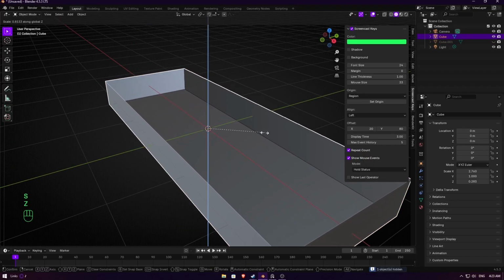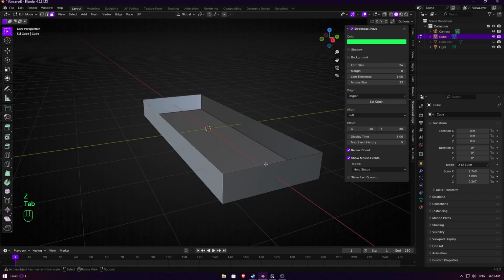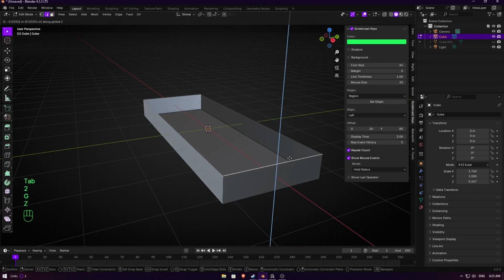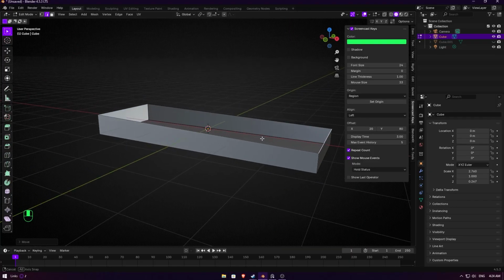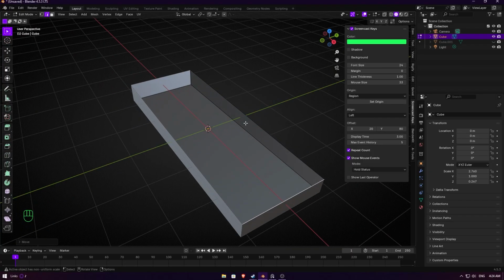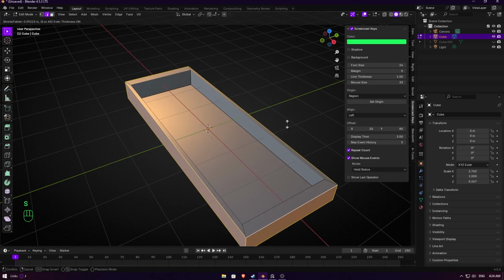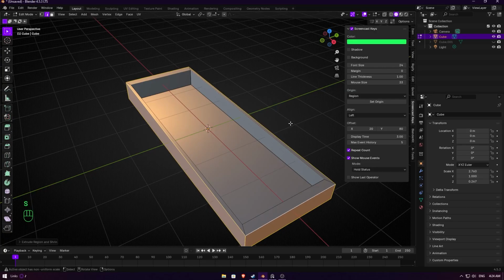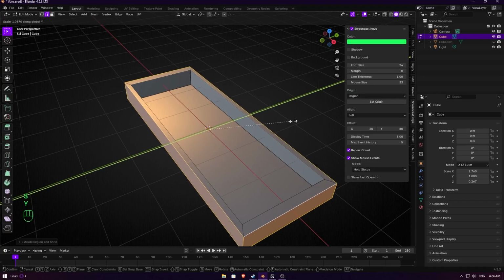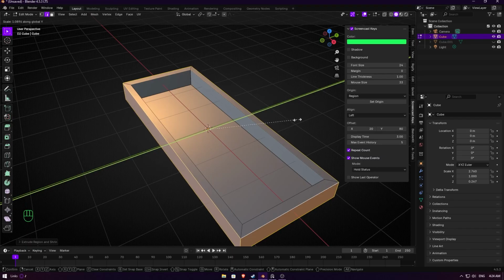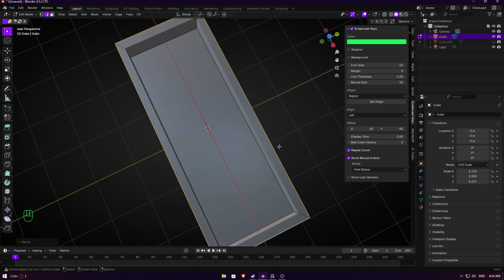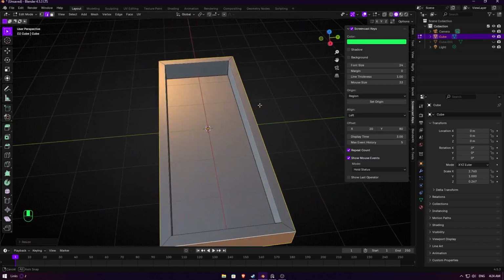And then we go here, maybe bend it a little and change this to lower, something like this. And next one, maybe I'm gonna select everything, Alt E and extrude along normals, and S, something like this. And I think here we go. So this is good till now.